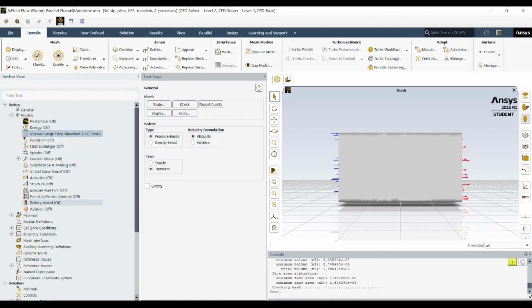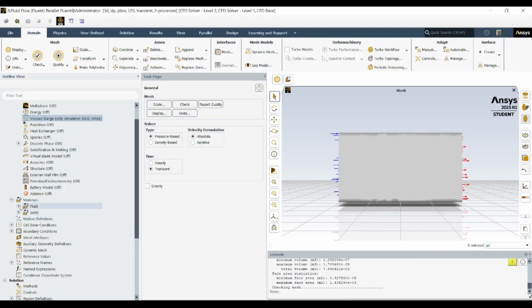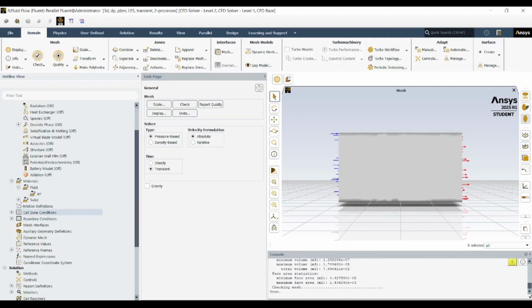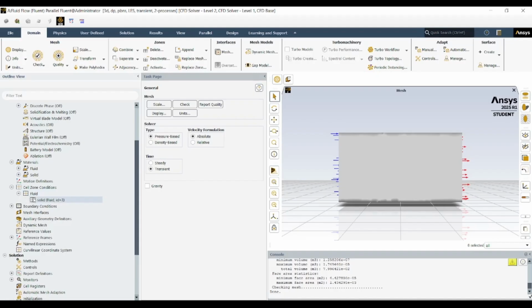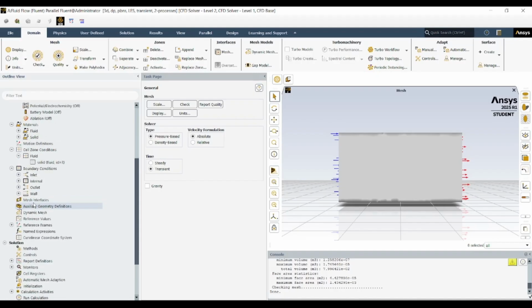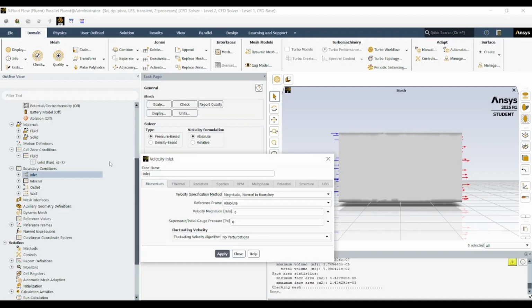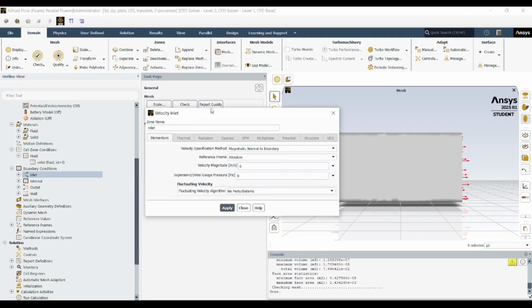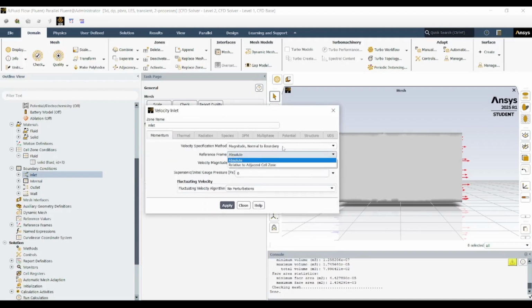A deeper part of the cylinder flow analysis comes from visualizing and plotting the flow results inside ANSYS Fluent and CFD Post, which transforms your raw numerical data into physical understanding. Once your transient or steady-state simulation has converged, you can start generating graphs, contours, streamlines, and animations to interpret the behavior of the flow over the cylinder in both qualitative and quantitative terms.